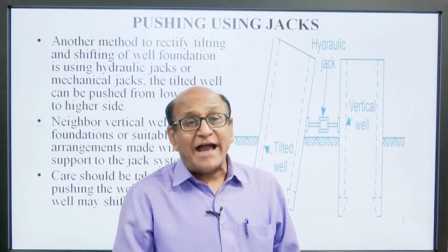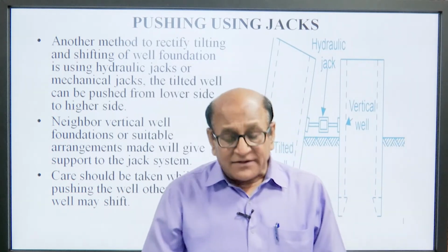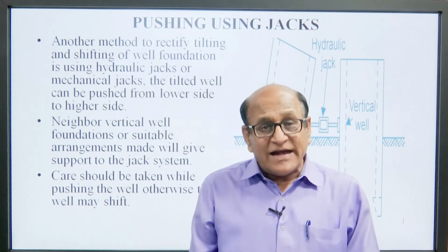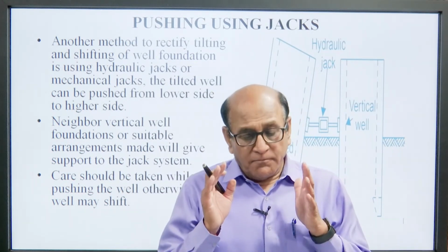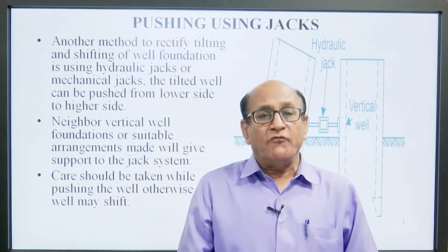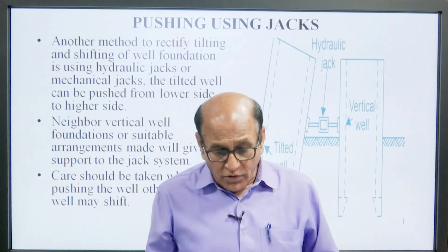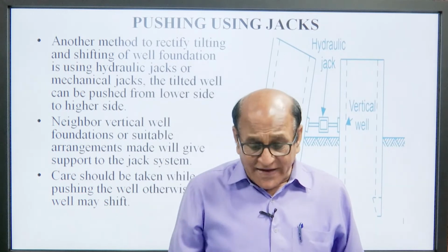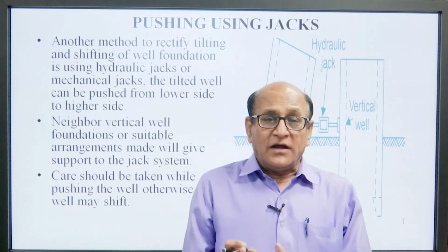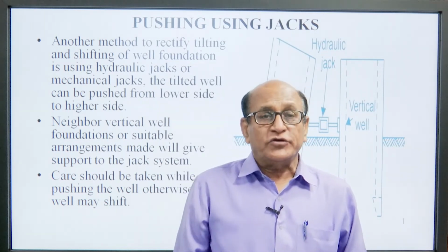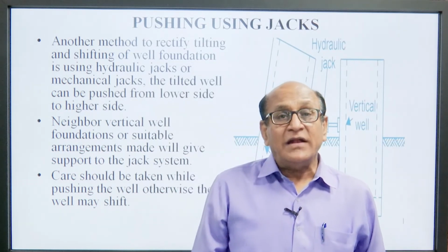Pushing using jacks: if it is inclined, then the tilted portion of the well is pushed by a hydraulic jack, so that it may exert force to make the well vertical.